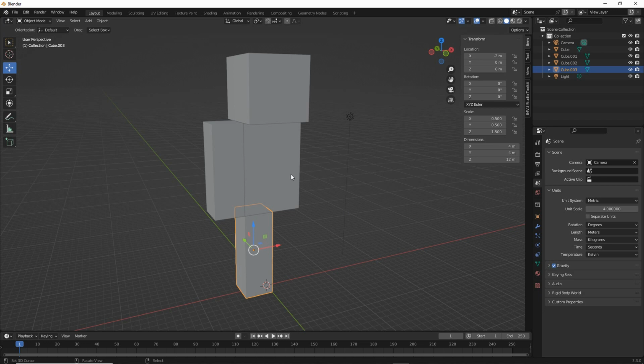What we want to do before we go any further is reset the meshes so the scaling is 1 for each of the X, Y and Z coordinates for each of our objects. So they differ slightly depending on what the object is, because we rescaled our basic cube.